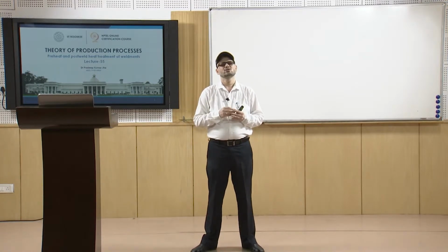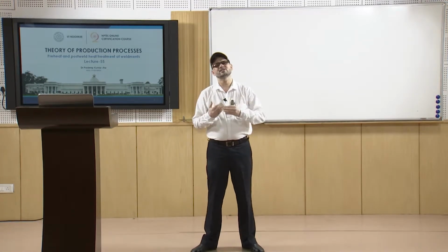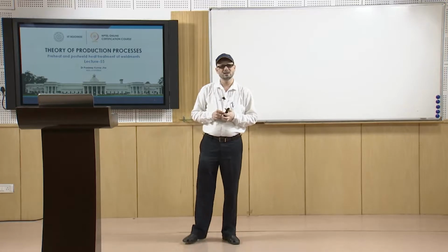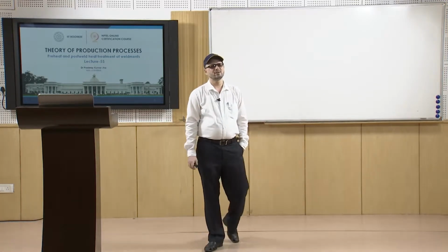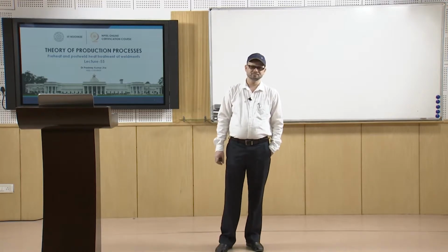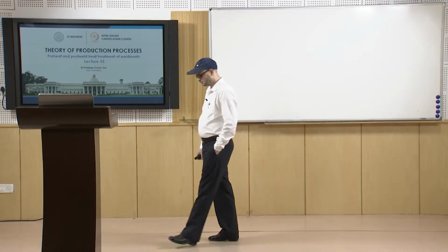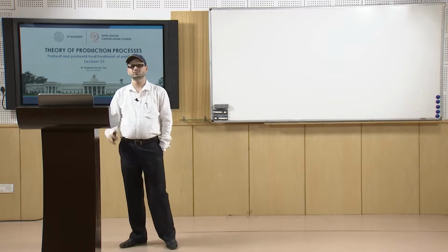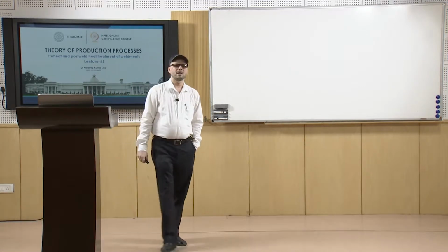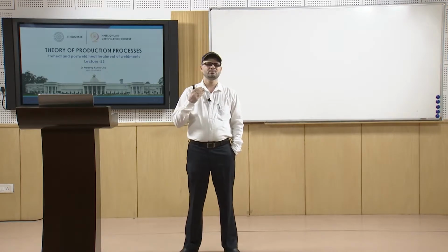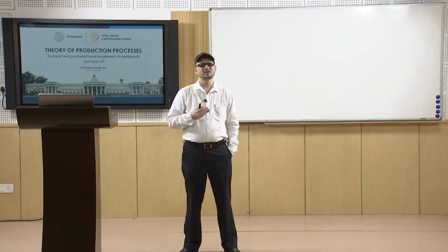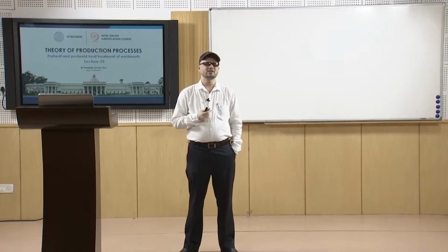If brittle phases are present or brittleness occurs, there is a chance of catastrophic failure of the welded component. That is the challenge with these preheat and post weld heat treatment processes, and that is their importance.